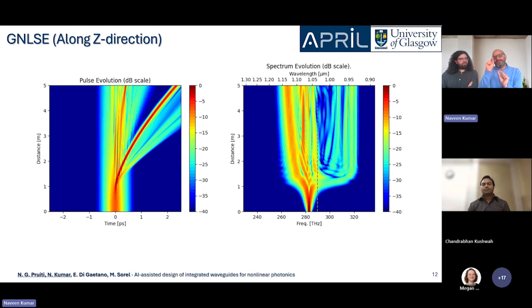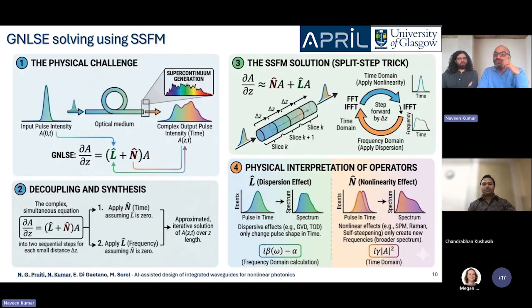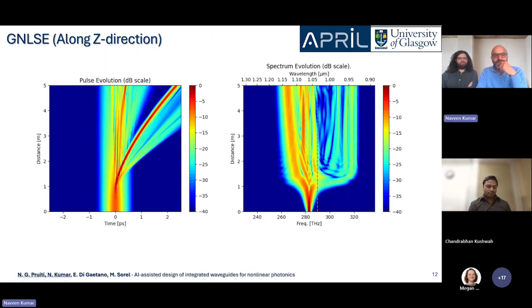Your material properties, that is, the beta propagation constants, do not remain the same. They change with widths along the slices. So we will have to repeat the third step again and again, where delta Z is changing with delta W as well. That is what we are currently working on.